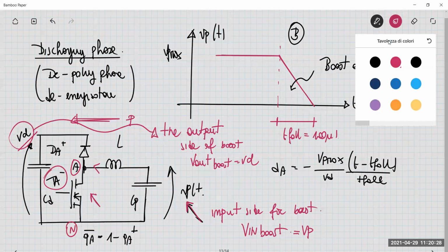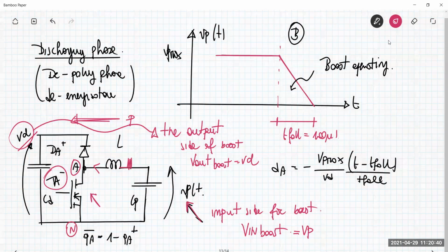The problem is that we are neglecting some parasitics. Okay, students of power electronics, I liked that they remember the same discussion we had in the course. We have this resistance here that are parasitics, something that you don't want in your circuit, but you have due to the real elements you are using.